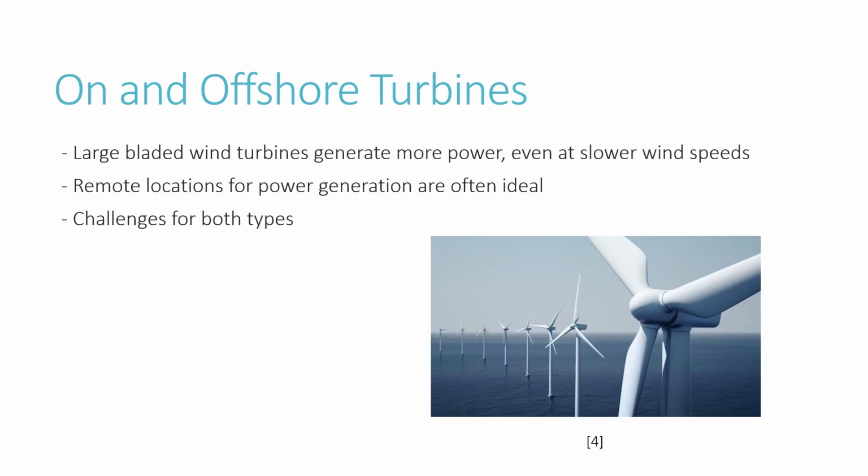With more surface area, more wind can be used to push the turbine blades, making it better overall, and especially in slow wind speed locations, to have larger bladed wind turbines. The problem for large onshore turbines is that they cause excessive amounts of noise, are a hazard for birds, can cause issues for radar, and can be in the way in a populated area.